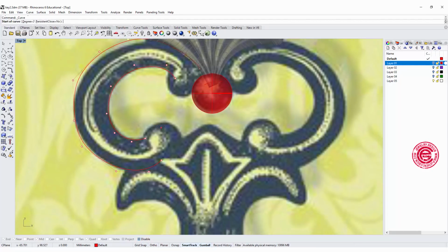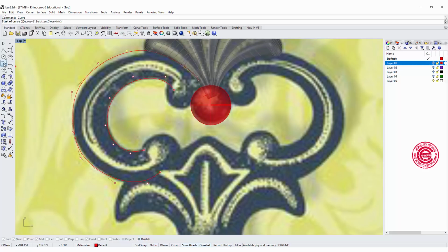Okay, so then we are going to create the circle. I'm going to use the diameter option because I'm going to snap into the endpoint right here and right here. Now you see that the circle is flat. We want it to be vertical. So going to the top, there's a Vertical option. You click on it, and it will be vertical right there. Let's do one more time. Endpoint to endpoint. Before you click on the second one, you want to use the Vertical option.